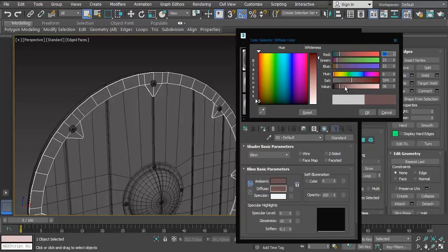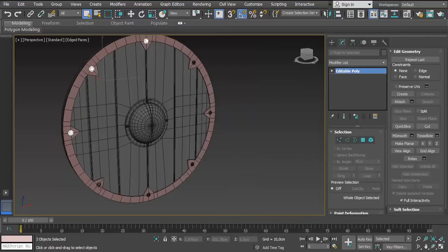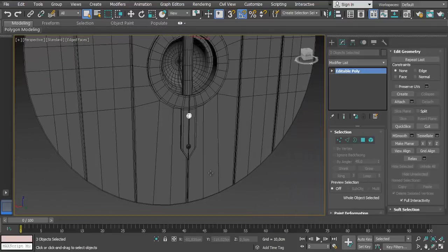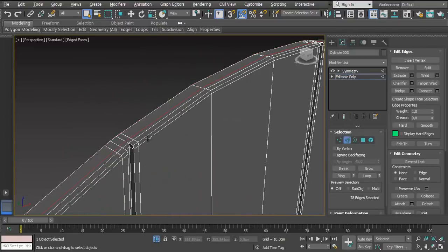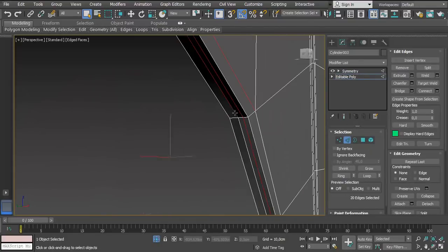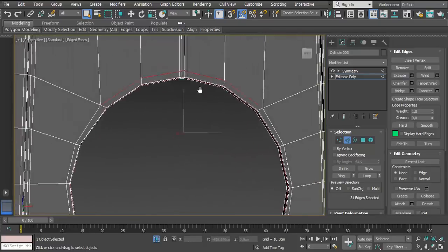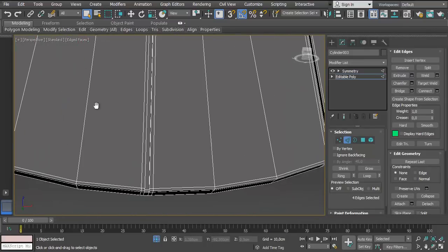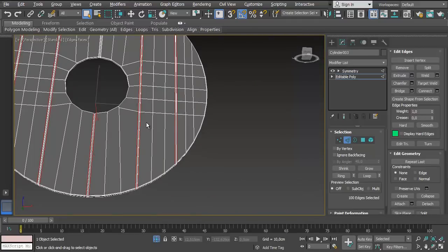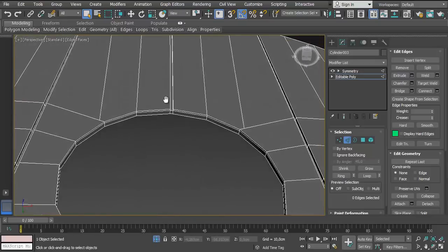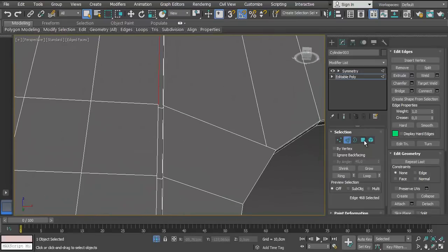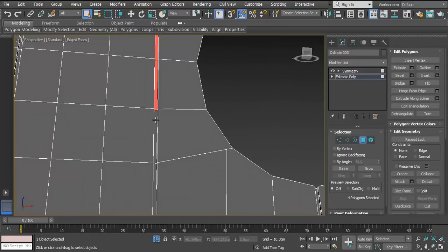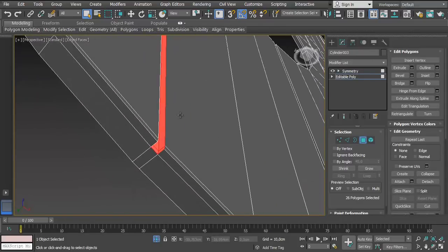The process to create a low poly version is something that is going to be easy to work with, but there are some rules that you need to follow. Obviously they're not super strict rules, but you do need to follow certain guidelines. For example, first of all, we need to remove the floating geometry that we talked about, and we need to remove the supporting edges. Here I'm trying to remove all the supporting edges that we don't really need. These extruded areas, empty spaces and carved areas, we don't really need them, because we are going to cover that in baking.